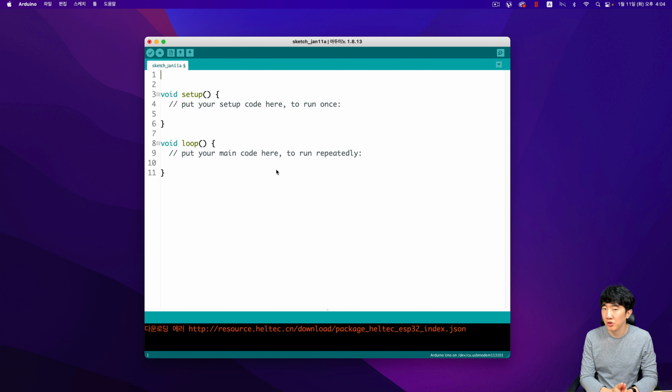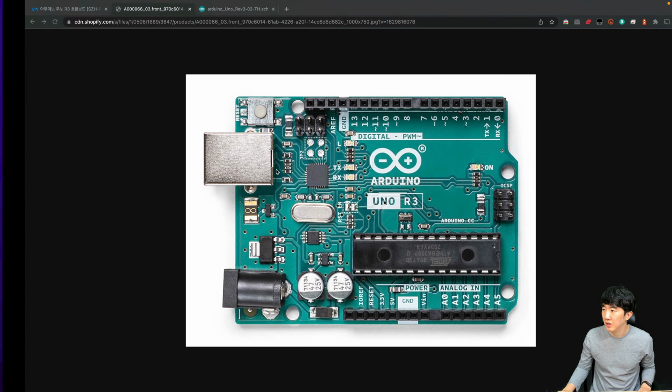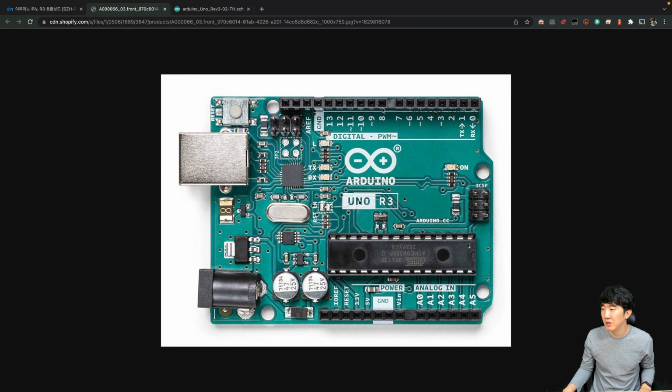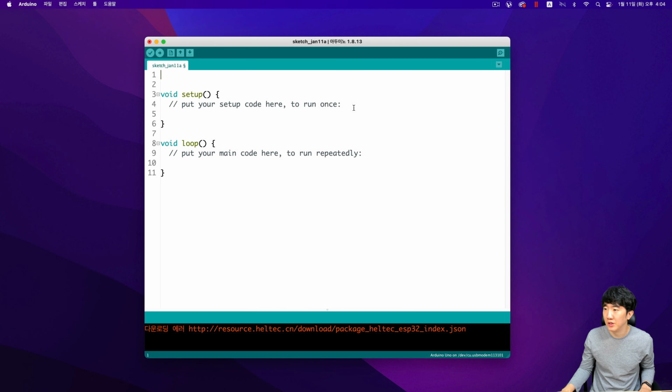Let's run the Arduino and write some code to control the digital output, which is a fundamental aspect of working with microcontrollers. This won't just end with simply saying that we can control the digital output. I will also show you how I actually write the code step by step, ensuring you understand each part of the process. In my case, I will use pin 8 to turn an LED on and off, which is a common beginner project to get familiar with digital outputs.